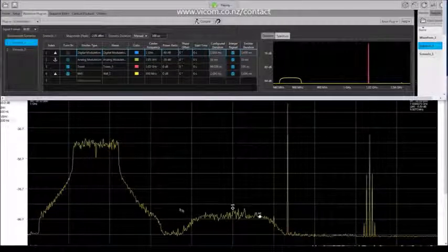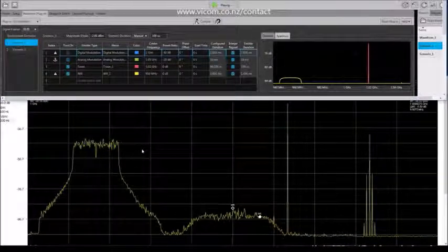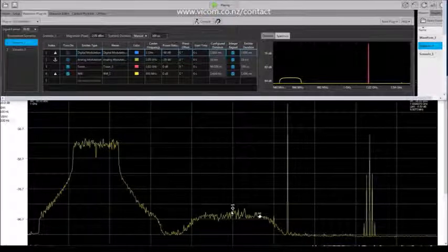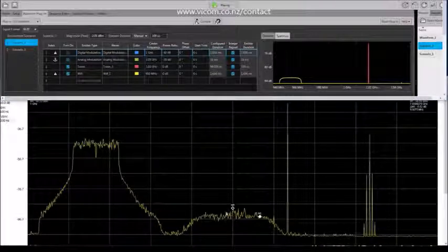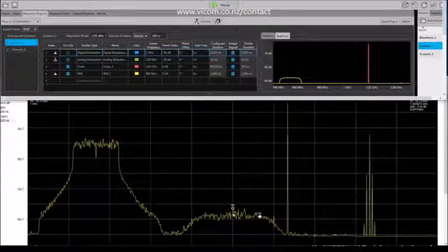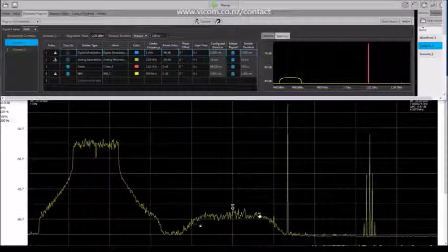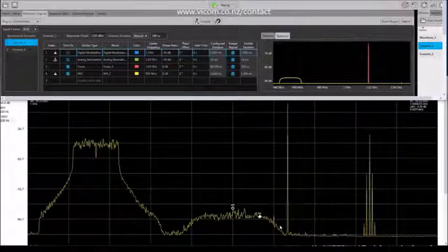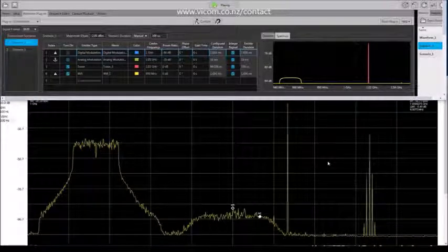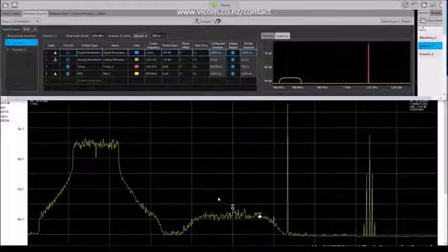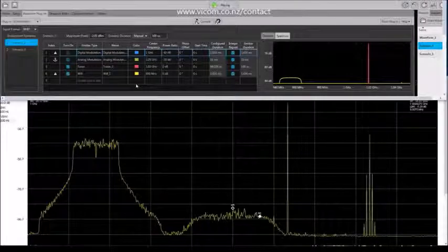So now I've configured it using 2 channels of the AWG, where we're power splitting the 2 channels, and you can see that now we've pulled up this 60 dB down signal, that we can actually see it using the full dynamic range of the AWG. So this is just another method of being able to view signals that are pretty much buried in the noise of a single DAC system. So this is a great capability that's also available when you're using the environment plugin for these particular types of testing.